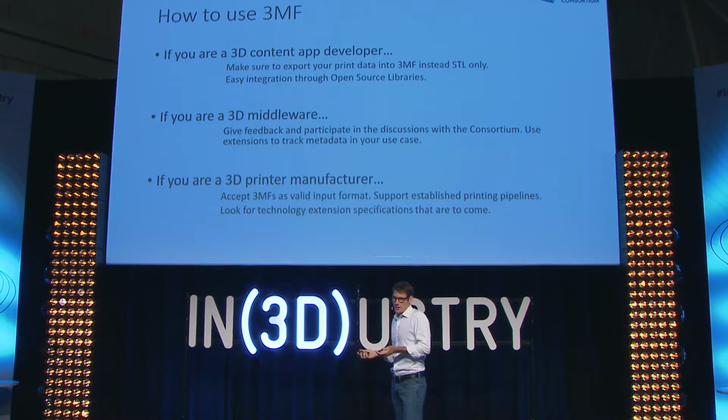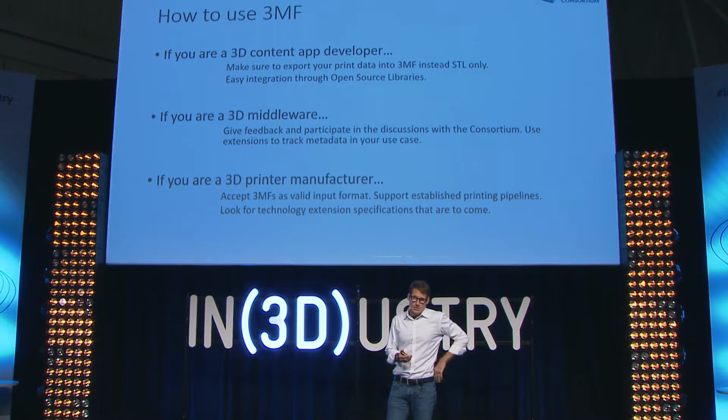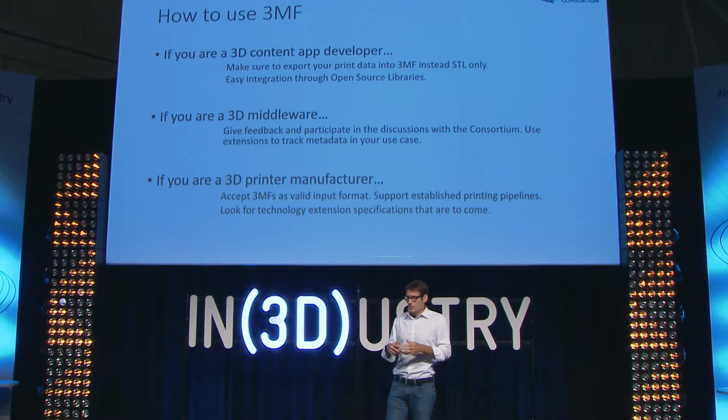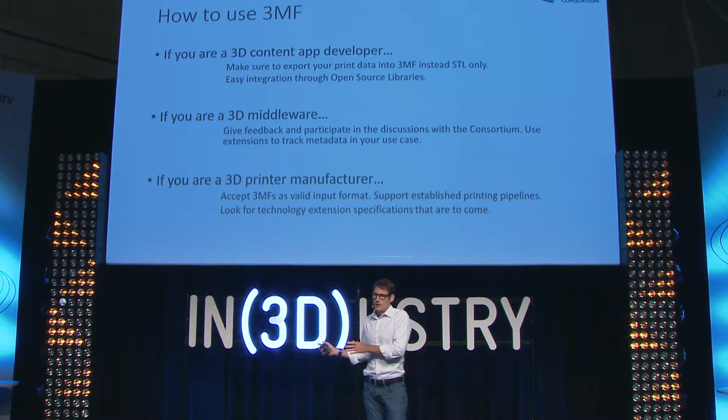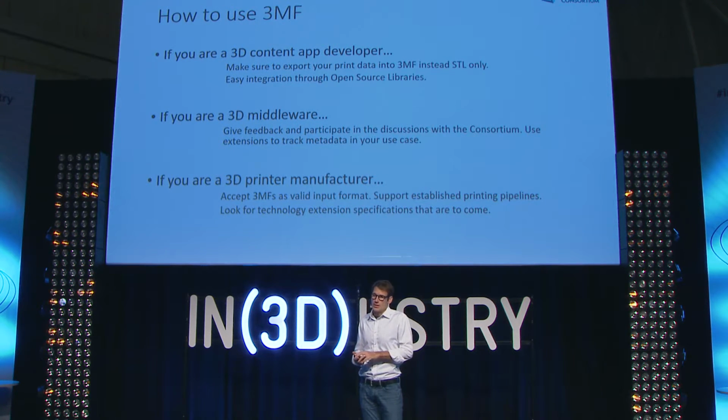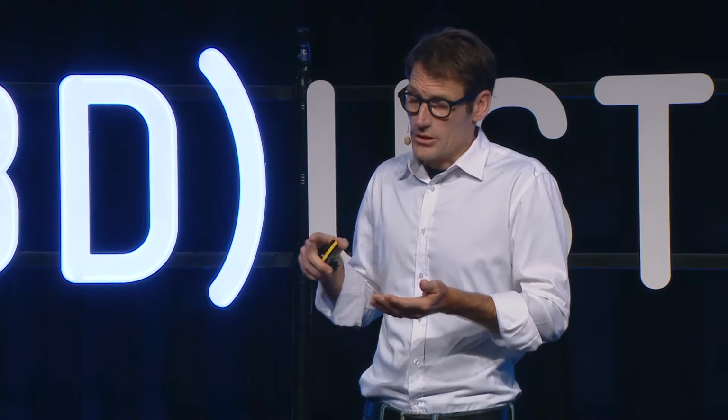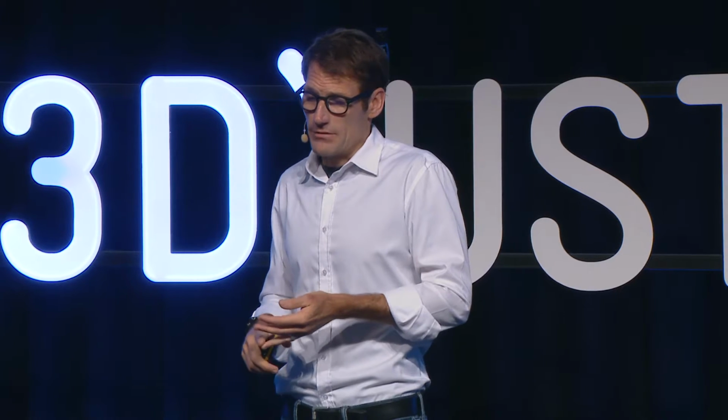Okay, so how to use 3MF. If you're a developer, a content developer, please start looking at the specifications and the code so you can export to 3MF instead of exporting to STL. There's plenty of support if you look at what's available on GitHub to help you bootstrap into doing that. I think what you'll find is that as you start to use it, it becomes much simpler, because the need for you to do a lot of fixing and fix-up should be greatly diminished, just because of the way the libraries are written and the way the format is specified.